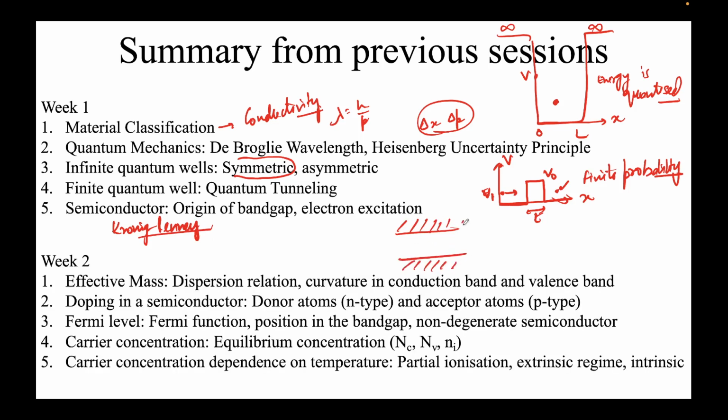So this is your EC, the conduction band, and EV, the valence band, and this is the forbidden energy gap, so electrons cannot reside here. For a semiconductor, this EG is some finite but small value, let's say up to 4, 5, or 7, 8 eV. Insulators have a larger band gap. SiO2, if you can recall, has a much higher band gap. Silicon is 1.1 eV.